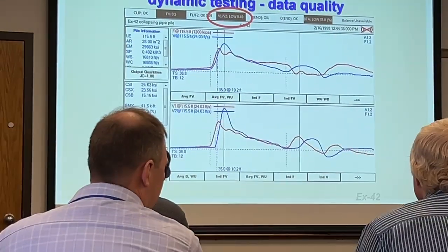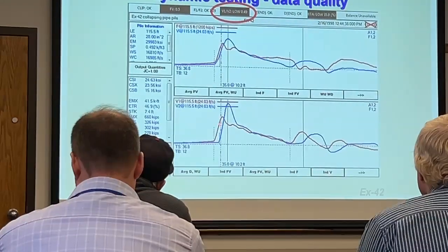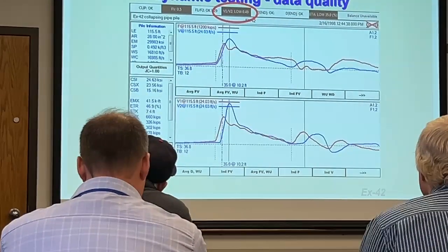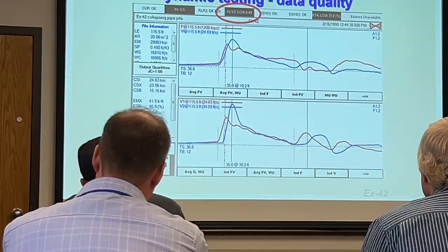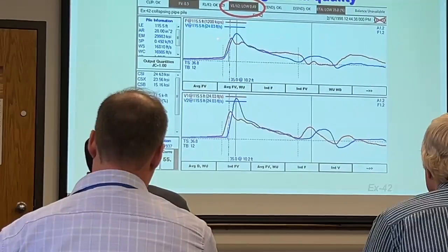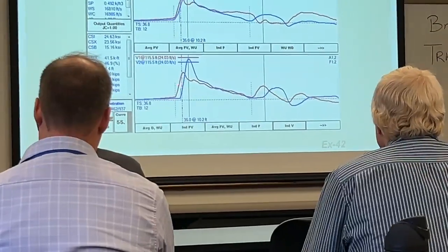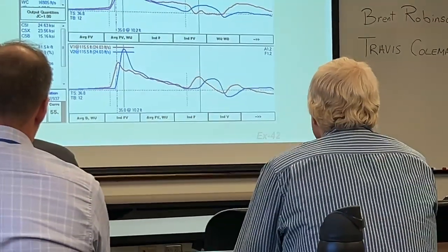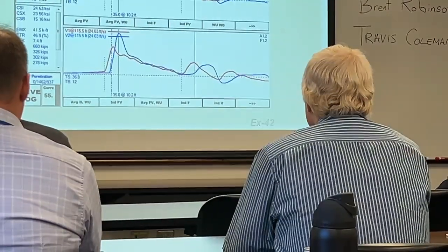It says that it's low, so we take a look. And we can see that there are 2 very different velocity curves. Remember, they should be the same. So when we look at this, we are seeing that one is sharp and very much in the same shape as our red force line. The other is delayed, has a much higher peak, and is looking like it's kind of moving around. So V2 in this case is loose.